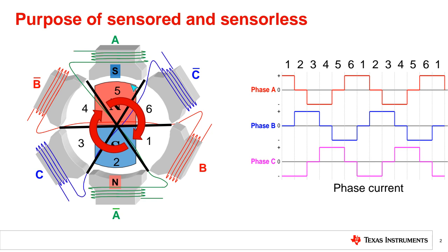It's important. If your motor moves from one to two, to do this, you must know where the rotor position is relative to the stator, so that you can apply a magnetic field that forces the rotor to move in the desired direction. Briefly, if you want to control your motor, you must know the magnetic field position. Good. Sensored control implies that you are using physical sensors.